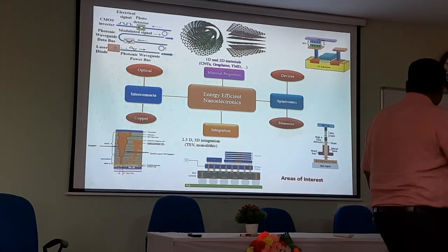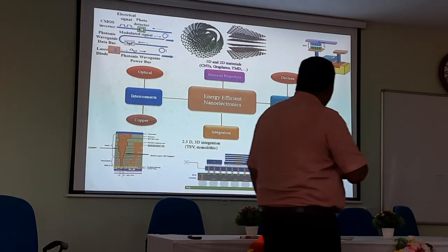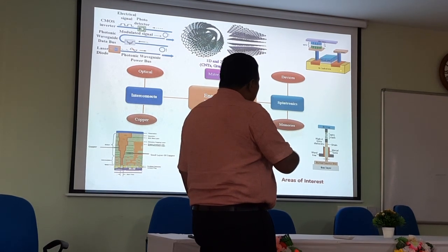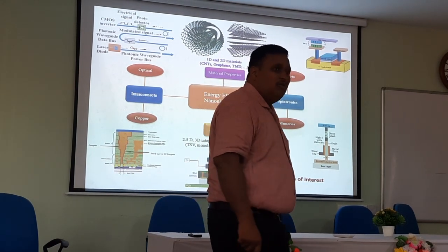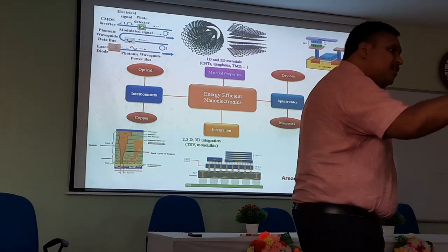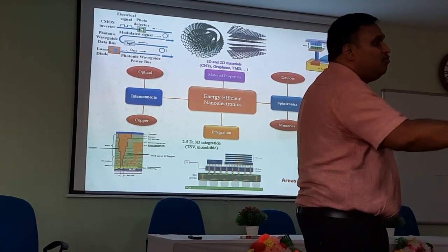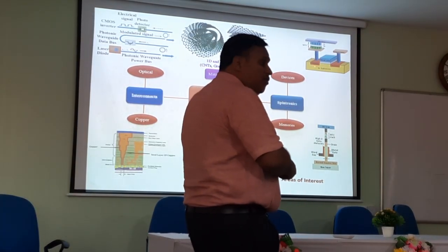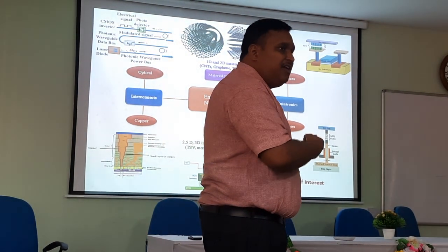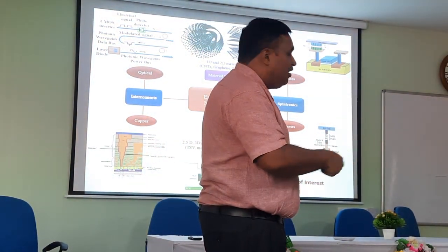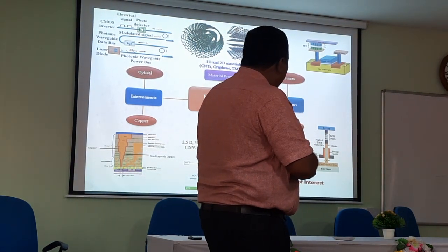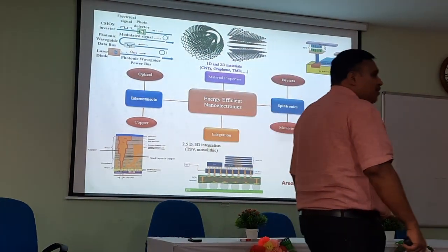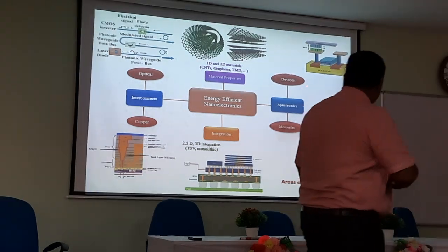Now, I'm just trying to make a comparison of DRAM and this one. What important thing you're seeing is, this size of transistor is fine. Is it that the MTJ is taking the silicon area? No. Whereas in DRAM, the capacitance is taking the silicon area. It is trenched into the silicon. When you talk about MTJ, it is hanging over your transistor. It's a 3D kind of structure, nothing to do with your silicon area. Apart from this, the MTJ is of very small size in comparison to your transistor. This is a planar transistor.